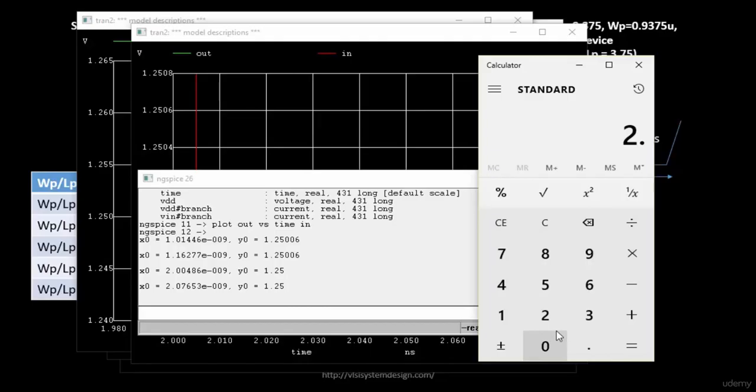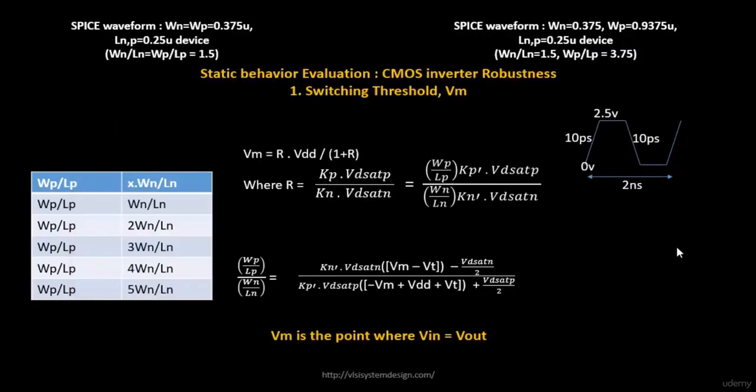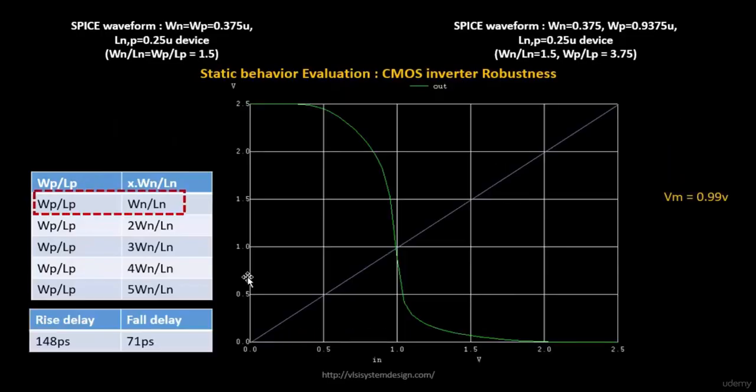So you'll see a difference between the previous SPICE simulations and this one. In this case, the set plot will tell you it's a transient analysis. In the previous case, since we did DC transfer characteristics, it was a DC one. In this case, we are doing a transient analysis, so it's called tran2. So we'll put tran2, and let's see what plots are available to us.